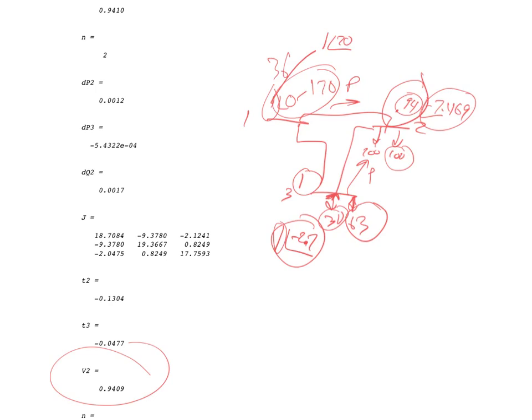So in this case, remember how we talked about solutions that aren't real or not converging? That might be a case where you have non-convergence because you just can't get 30 megawatts of real power out of the system. So your slack bus, you don't want it set sky high because you have some problems actually doing that. And that's the only bus that we can set the angle on, correct? The only bus that we can set the angle on is the slack bus. The generator bus, we have to solve for it. The load bus, we have to solve for it. Okay?